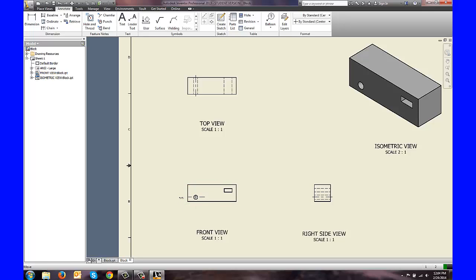All I did was move my mouse over to the center mark until you see these little green dots show up, and then I'm putting my mouse on it and using the left mouse button and just dragging them out. The reason is that I want to be able to add dimensions to these lines, and I want to go towards the end point. So it shows a little bit more detail where that hole is.